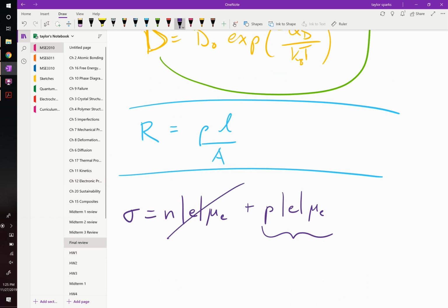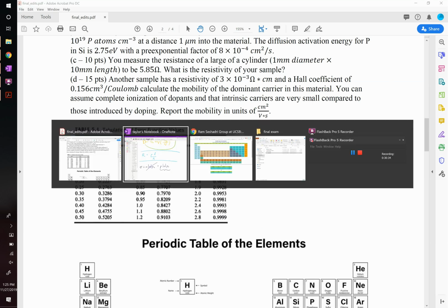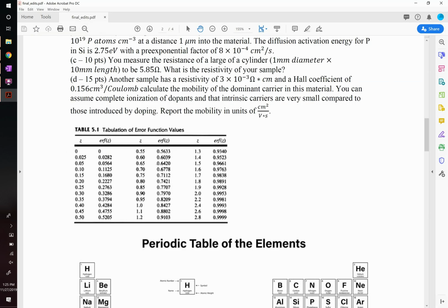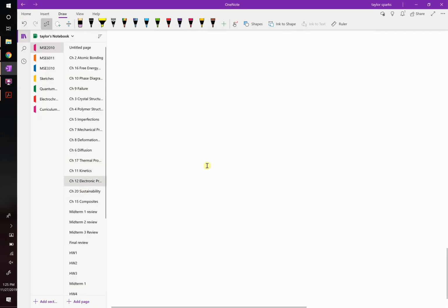So it doesn't matter, so that's the absolute value of e, or are you using the case around that? The Hall coefficient itself would be equal to a negative number if it was electrons. Since it's reported as a positive number, it's holes. In fact, that's how this measurement works to tell you holes versus electrons.